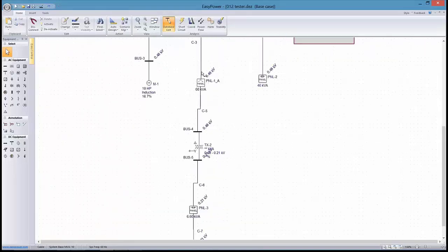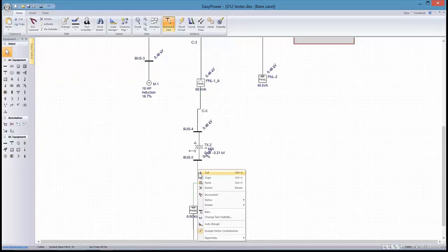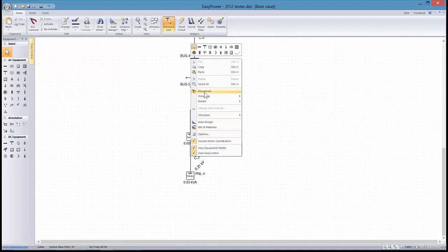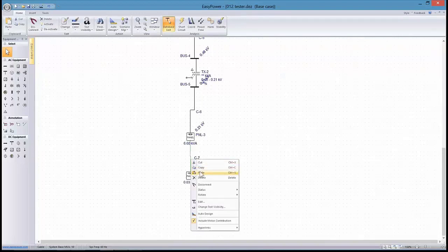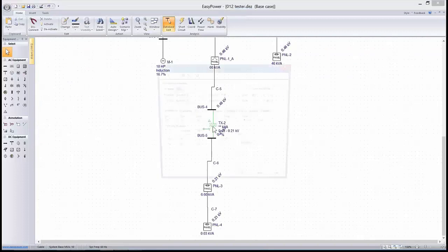Let's take a copy of this cable and paste it here. I guess we also need to update our transformer. And clearly you wouldn't need as heavy a cabling as we used up on the 480 volt bus, but for purposes of speeding up the process, we're using the same size cable that we used on the 480.